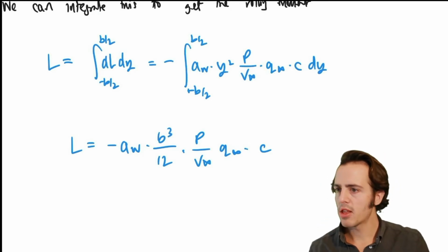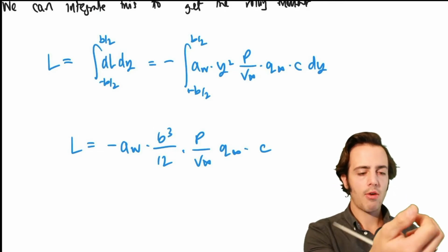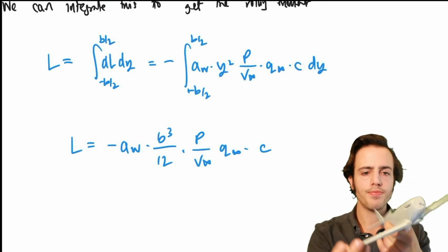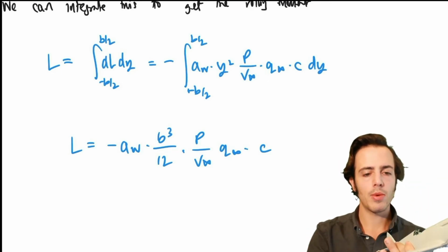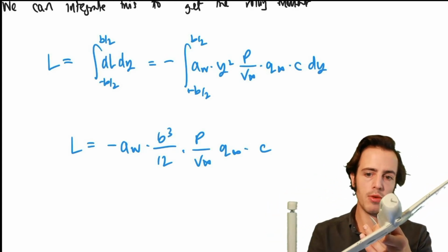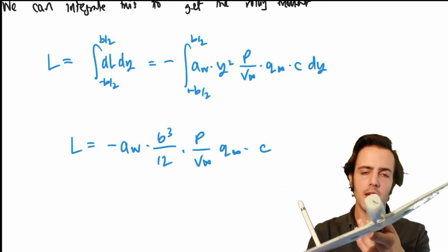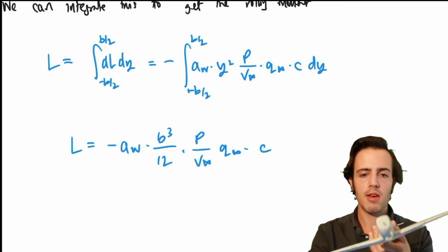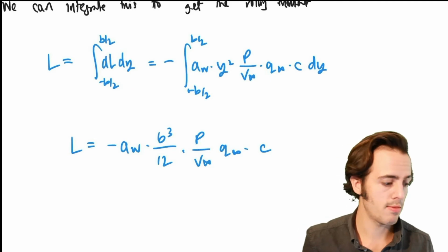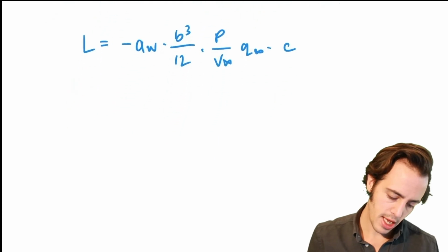Let me make sure my camera is flipped around so I'm not doing this back to front. Stick my right hand out through the aircraft, then the aircraft x-axis, and my fingers curl around, giving it a starboard wing down roll rate. Starboard wing down roll rate means I've got more lift being produced here, and less lift being produced here. I've then got a moment that's restorative, which is a negative moment. So the sign of this makes sense, and it shows us that we haven't messed up in our algebra or our calculus.